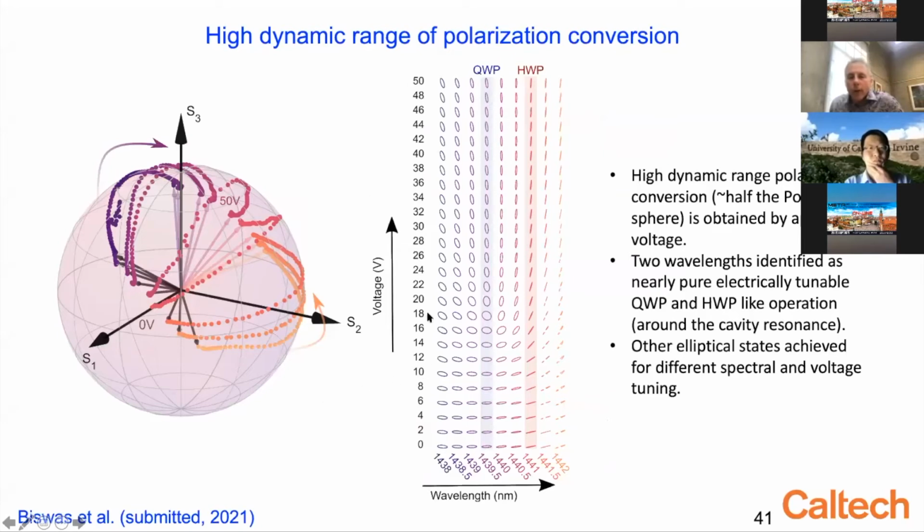And this shows here the tunable polarization, for a given frequency and a given cavity structure, the profile of the scattered beam in terms of its ellipticity, and you can see here, this is operating as a quarter wave plate going from approximately linear to circular polarization at this voltage state. And here a half wave plate where you can see the polarization rotation as a function of the applied voltage. So I really look forward to the introduction of new materials.